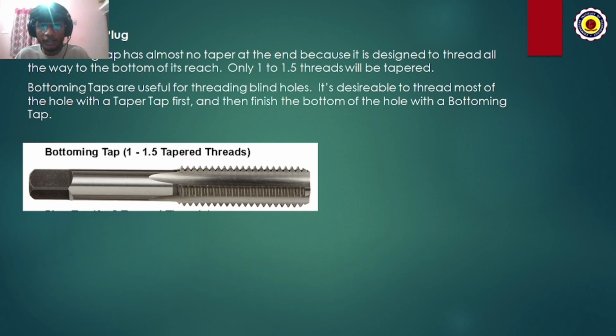Bottoming taps are very useful for threading blind holes. It is desirable to thread most of the hole with a taper tap first, and then finish the bottom of the hole with the bottoming tap.